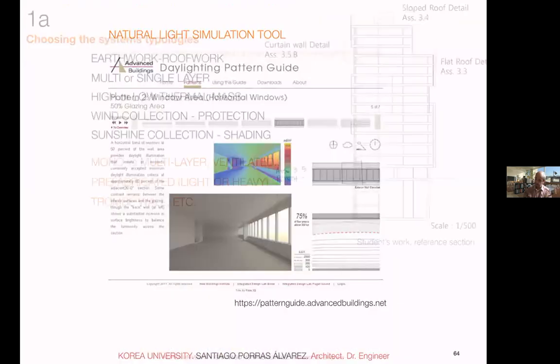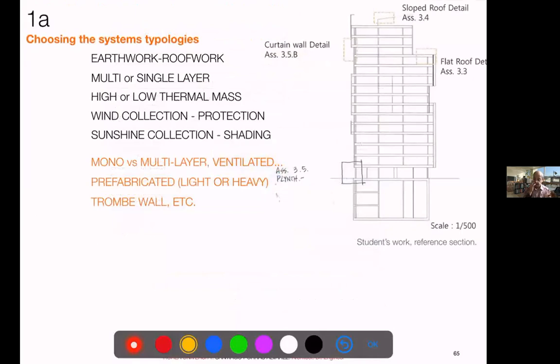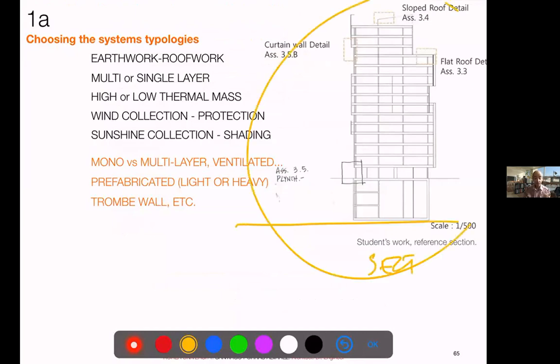Before, we just had to guess ourselves. So once we have those studies and we know how much work it will take, we have to start, usually from the section, right? We have to identify the difficult points, which are usually the plinth, the typical walls, and the connections with the roof, right? These are like three or four points we always need to work on.